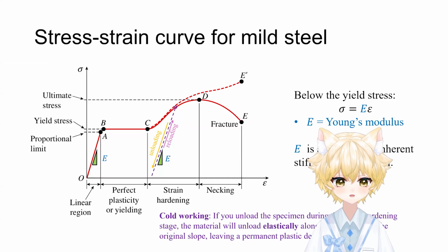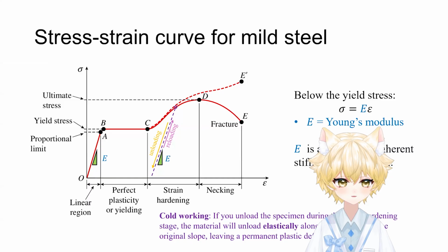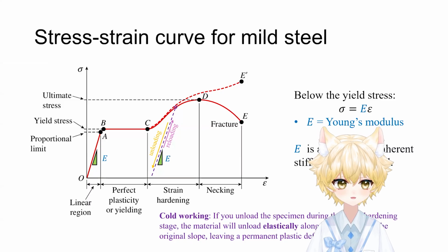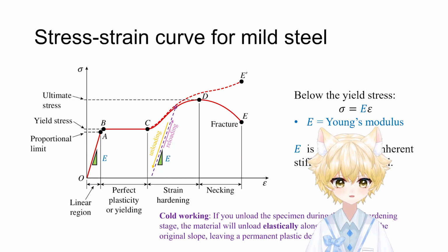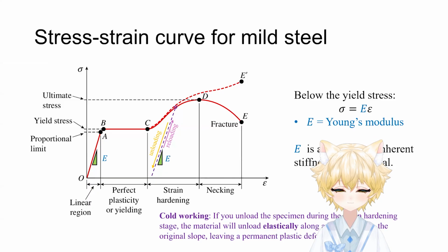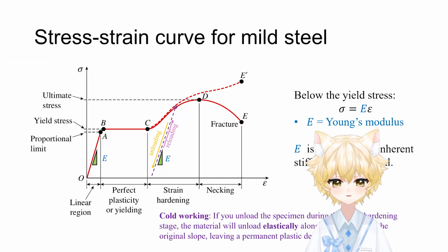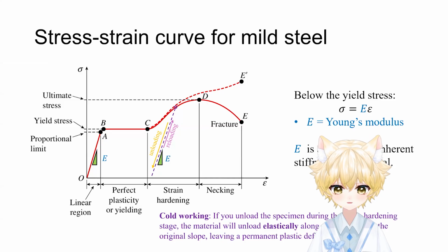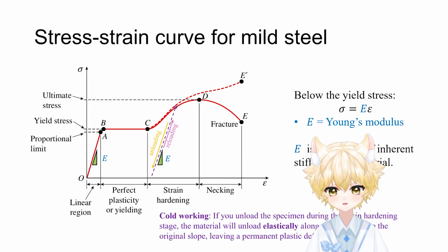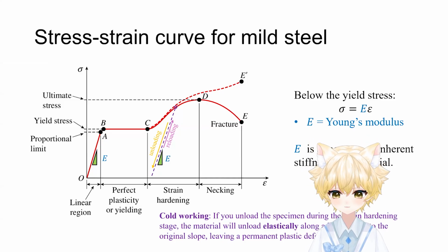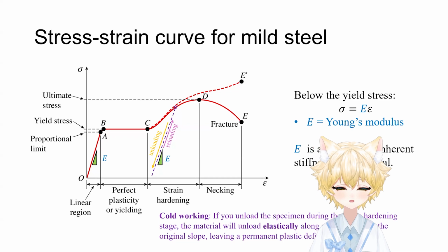Finally, a quick reminder on true stress and nominal stress, as indicated by the dashed line and the solid line. Physically, we know the cross-section area shrinks as we pull because of Poisson's effect, which increases the actual stresses. That is called true stress.